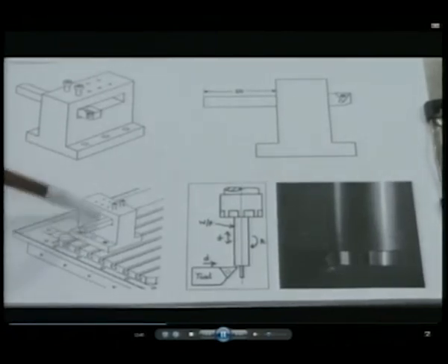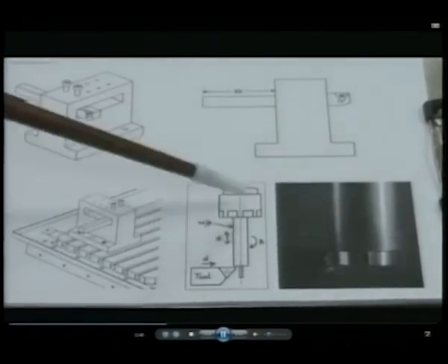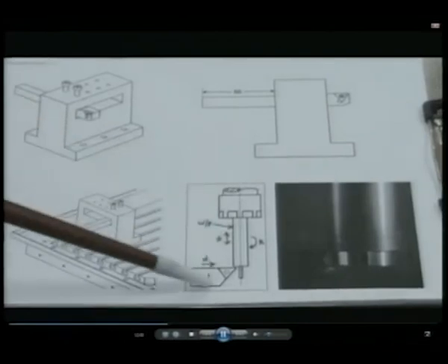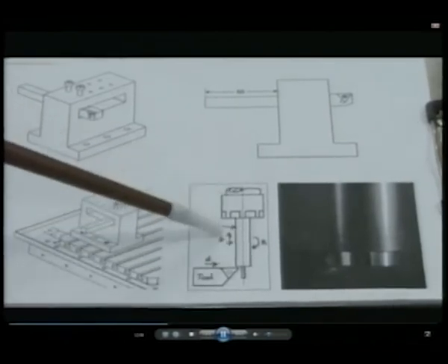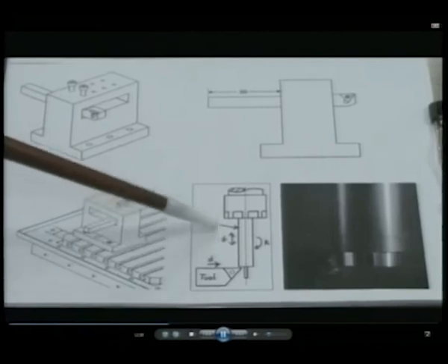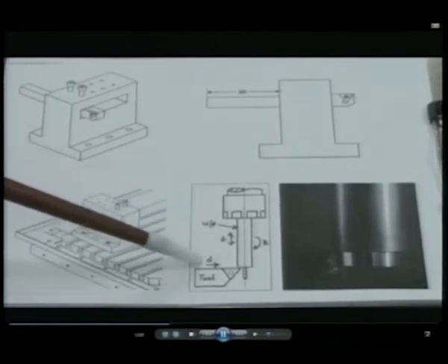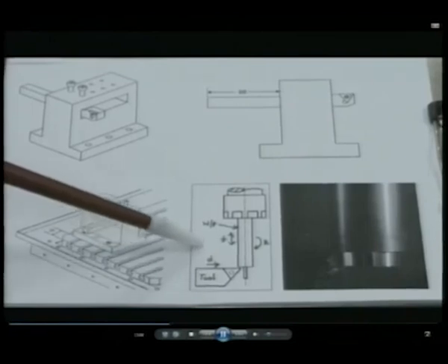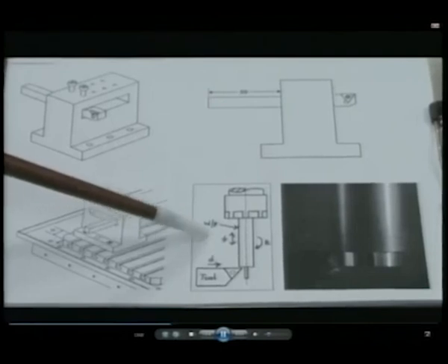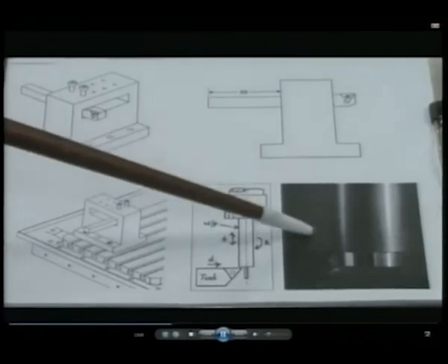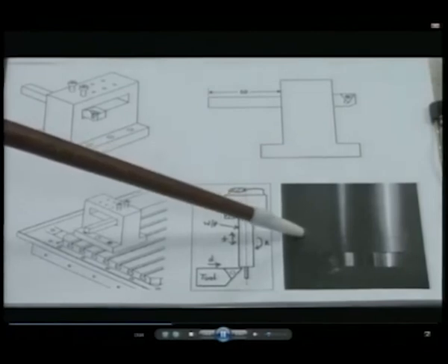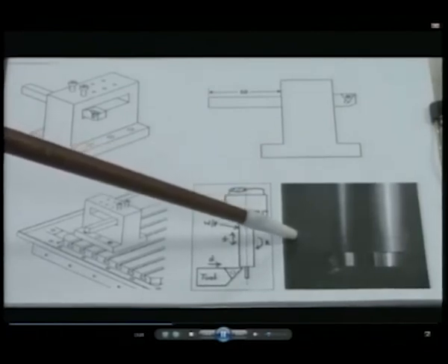In this operation, the workpiece is fixed in the spindle and the tool is clamped on the table. The workpiece rotates and is given the feed motion, whereas the tool is provided only with the depth of cut. This is slightly different from the conventional machine, where the feed as well as the depth of cut is given on the tool. This diagram shows the turning process during machining in the micro tool machine.